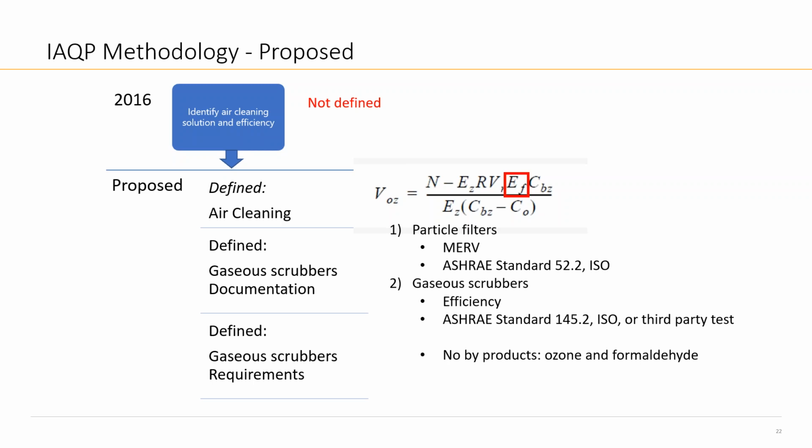So in summary, you can have a different third-party test as long as, and I think this is the important part, you can document the conditions of your test. And more important, if you want to test efficiency, you need to make sure that you apply it in the field in the same way. To give you an example, what is the required CFM, or how much can a piece of electronic device clean? What is the area? What is the CFM? What is the voltage? And do the efficiency test and the byproduct test for the same settings. I encourage this to be done in a third-party evaluation test.